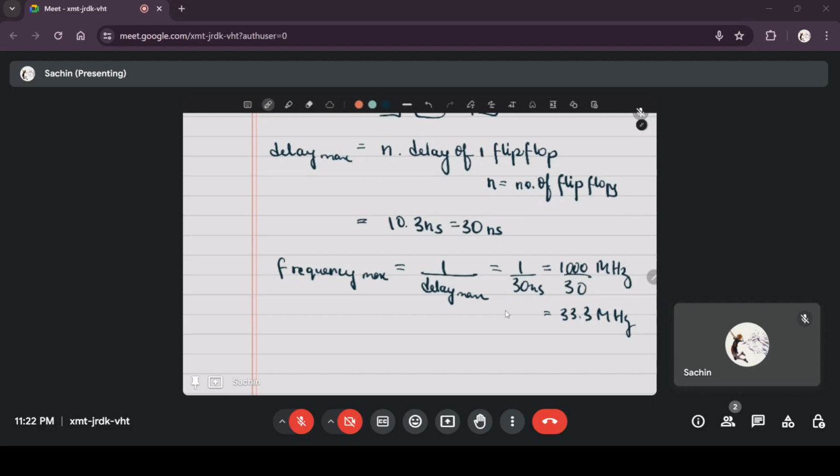So if you don't have a time period of at least 30 nanoseconds, then the time period is smaller than that, and the change in the output would not have even fully occurred. So from 1111 at 15 nanoseconds, you might not even have changed your output to 0000.